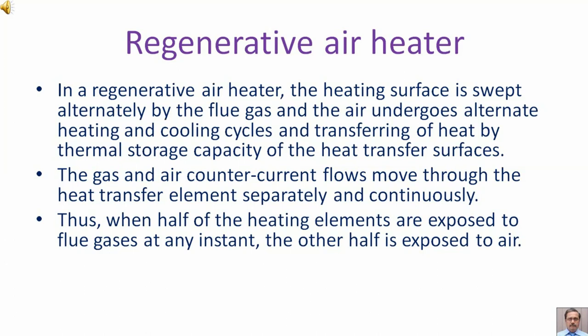The gas and air counter current flows move through the heat transfer element separately and continuously. Thus, when half of the heating elements are exposed to flue gases at any instant, the other half is exposed to air.